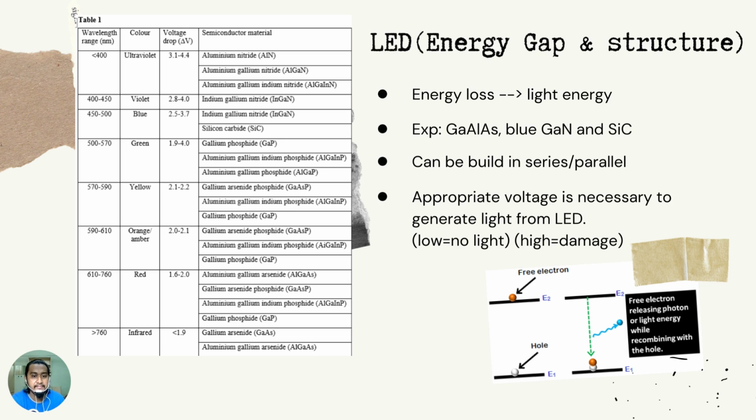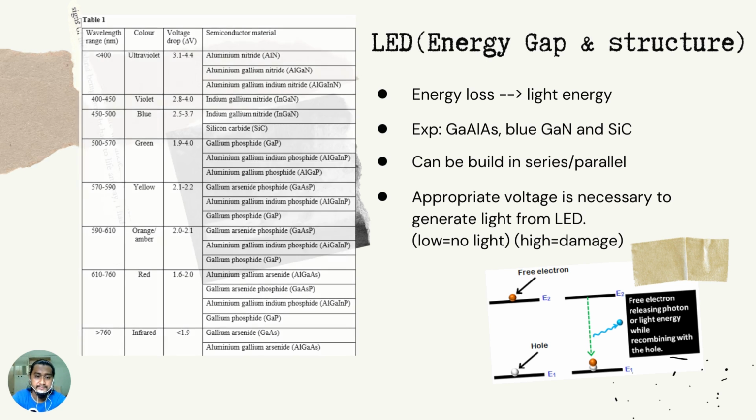When designing a parallel circuit, pay close attention to the amount of current necessary to travel through each LED, because each LED has a different forward voltage. Connecting them in series would be more complicated. If the voltage supplied by the source of electrical power is insufficient to excite the LED chip, the discrepancy will turn off part of the LEDs. High voltage, on the other hand, causes damage to an LED with a low forward voltage. Generally, LEDs used in a series must have the same forward voltage, or not differ a lot, for the circuit to function effectively.